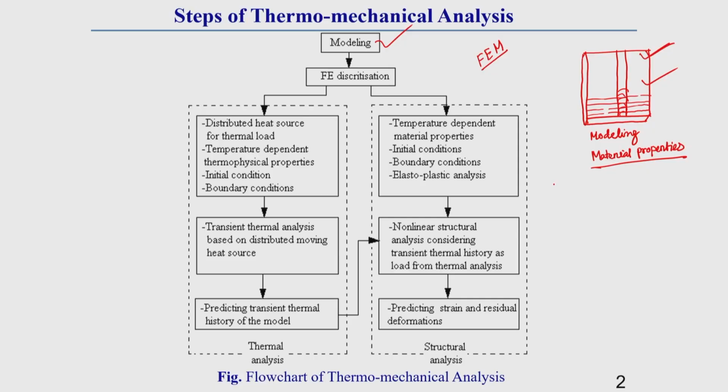You know that welding residual stress analysis is an elastoplastic thermomechanical analysis, or thermal mechanical analysis. By this elastoplastic thermomechanical analysis, we can find out the residual stress distribution in the weldment. So, it consists of a thermal analysis as well as a mechanical analysis.